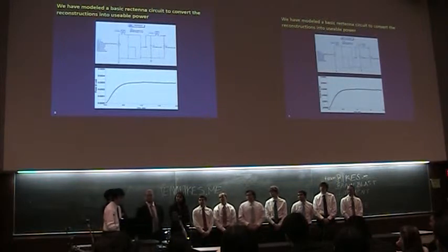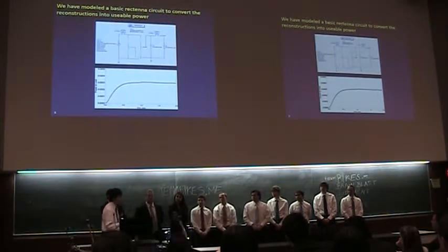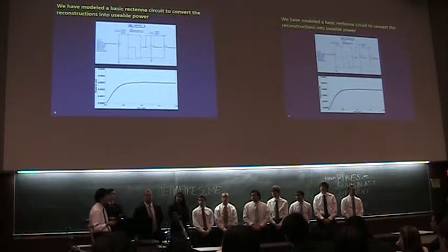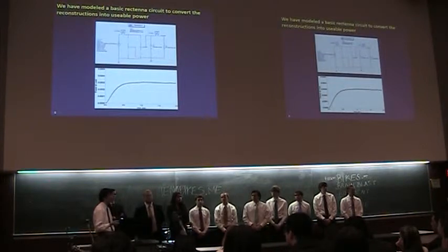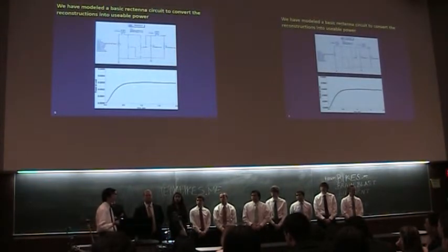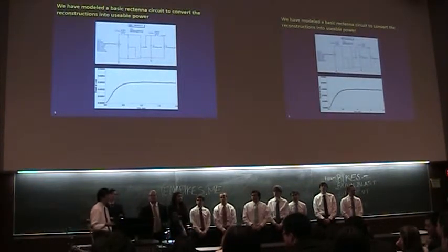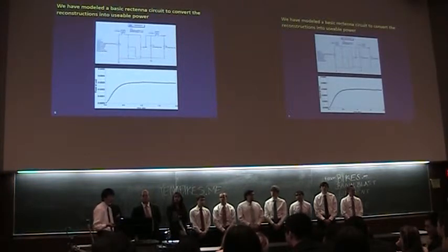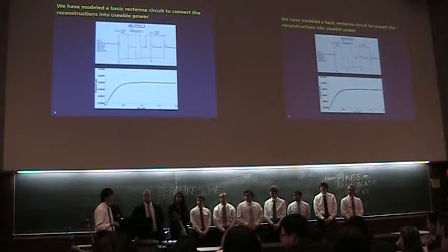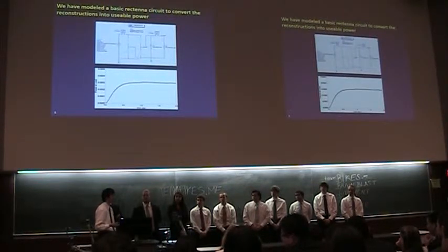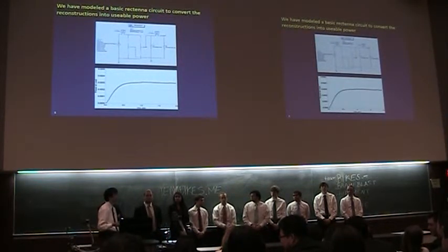If we want to talk about the switching speed of the diodes, there are a lot of different factors. You want something called a Schottky detector diode, which has a cutoff frequency in the 18 to 20 gigahertz range. So for our applications, that would be sufficient. We've actually tried experimenting with a number of different diodes and only recently come across the frequency issue. So that's an area of current development.